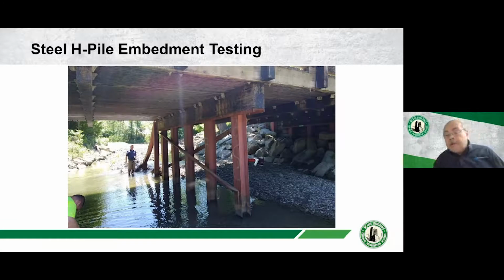Bridge load rating. This happened to be posted because there was deterioration in the flanges and the web of these 6 steel sheet H piles. So nobody knew how deep they were, and before they wanted to excavate down, so a splicing or a jacket repair option could be implemented, they needed to know the bedrock. So the refraction survey pointed out the bedrock's about 22 feet down. We tested each of these piles very quickly, and the embedment length, you guessed it, about 22 feet deep.